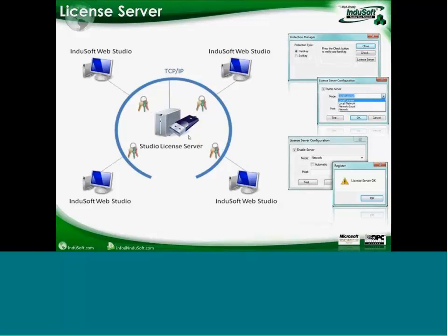So, for instance, if you have a hard key in this server, and this hard key supports 4 stations, you can have up to 4 computers in the same network running InduSoft Web Studio and sharing the information from the hard key connected to the server.